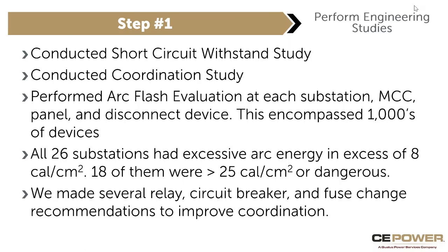So kind of step one. We did the short circuit coordination arc flash study. Thousands of devices, and really what we found was, of the 26 substations, the majority of them were 25 to 100 calories as far as arc flash hazard.